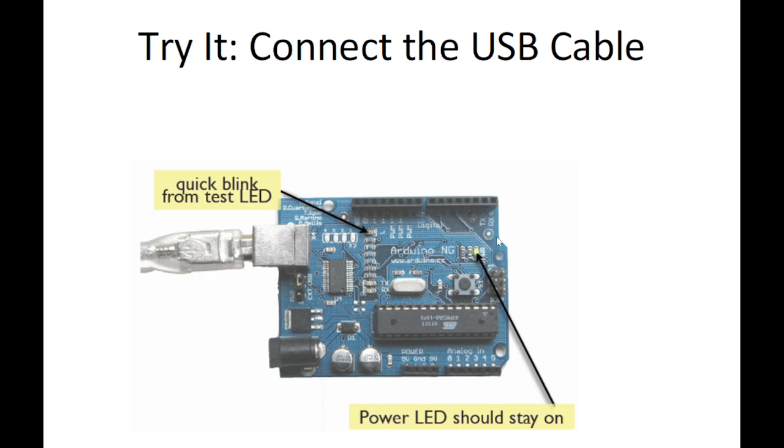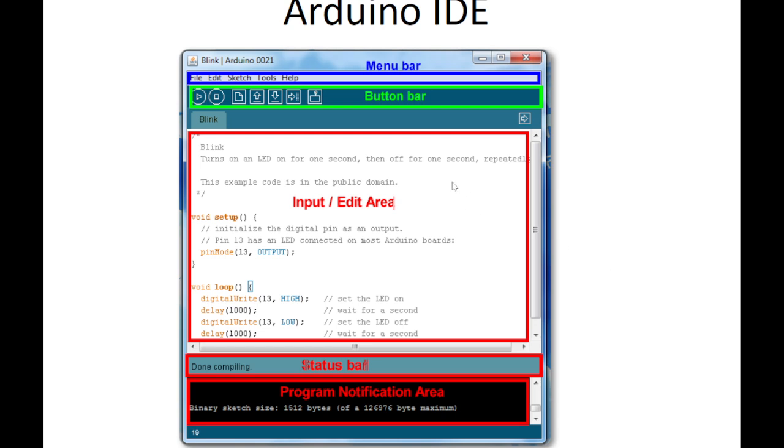So on the laptop, what are you going to do? Bring in your Arduino, and we're going to do the basic operation of blinking the internal LED. You will connect your USB cable on this connector. Make sure you see this power LED turning on, and then you open up the IDE, and in the IDE you write this code.